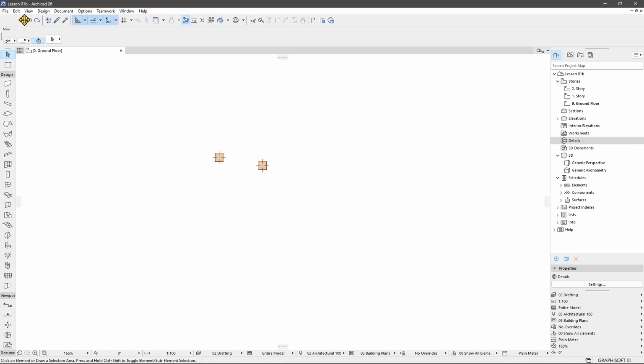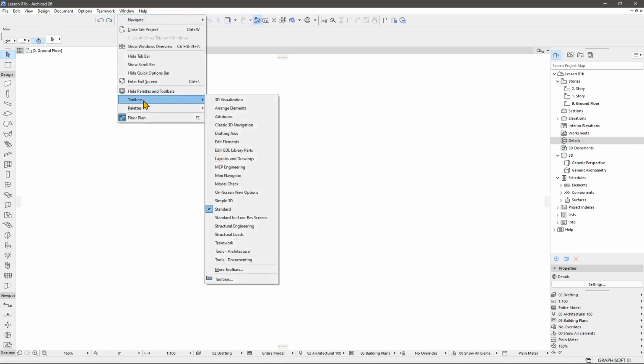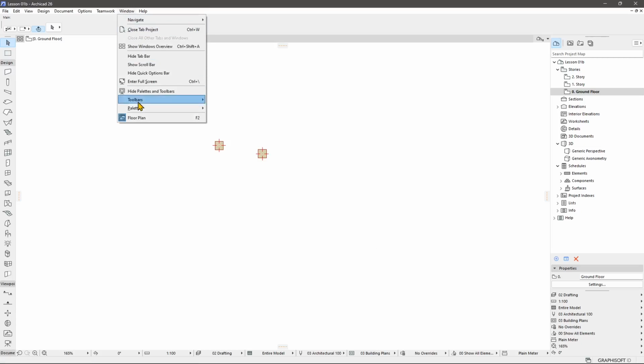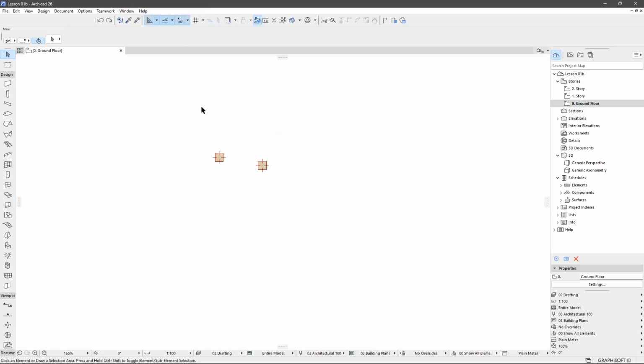Now, this is the main toolbar, which is right here, the standard toolbar. If you uncheck this, it's going to disappear. If you want to retrieve it, just remember, go to Window, Toolbars, Standard, and you can also add and customize with more toolbars. You have this left toolbar, which is more for bringing in objects, and this top toolbar, which has basic commands like undo, redo, and other things for the snap that we're going to see later. Now the bottom part, this is the properties as well.